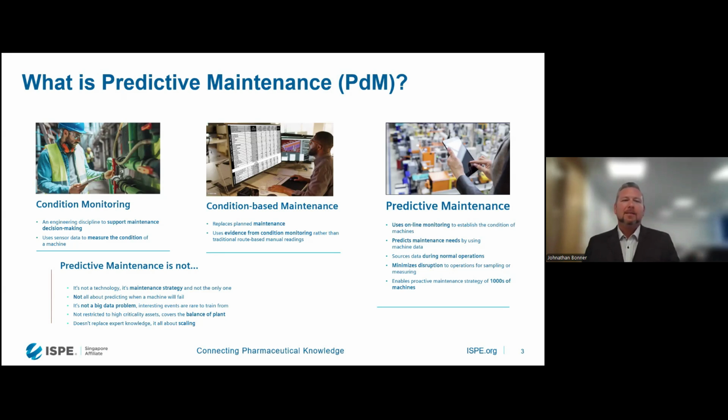So predictive maintenance is an evolution from traditional condition monitoring. But instead of having a specialist go around the facility, taking manual measurements, then uploading them to the computer, analyzing them, and reporting back on them, this function is now automated and online, so continuous. Also, with traditional condition monitoring, it was a snapshot in time. When I used to run condition monitoring programs, it would be once a month. You'd manage to get to that machine again on your route-based, time-based schedule, and you would take a snapshot to identify the condition of that asset at that time.